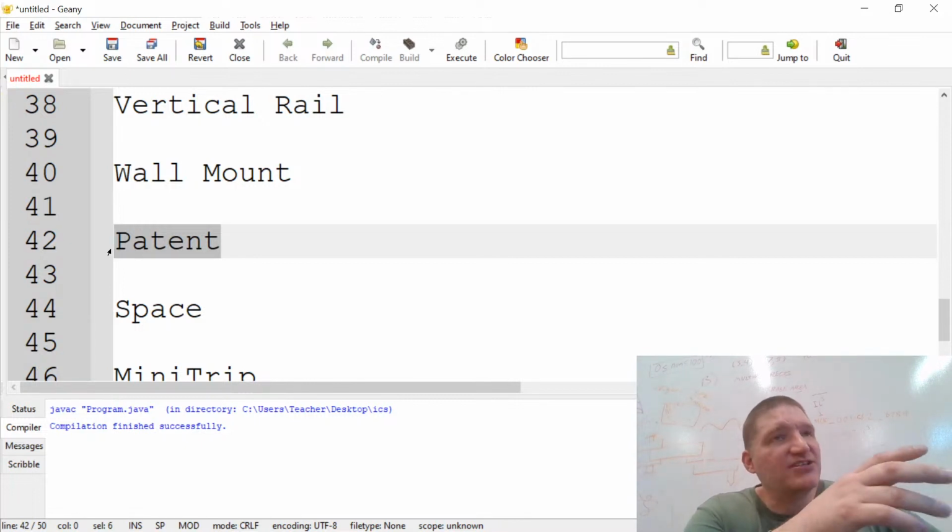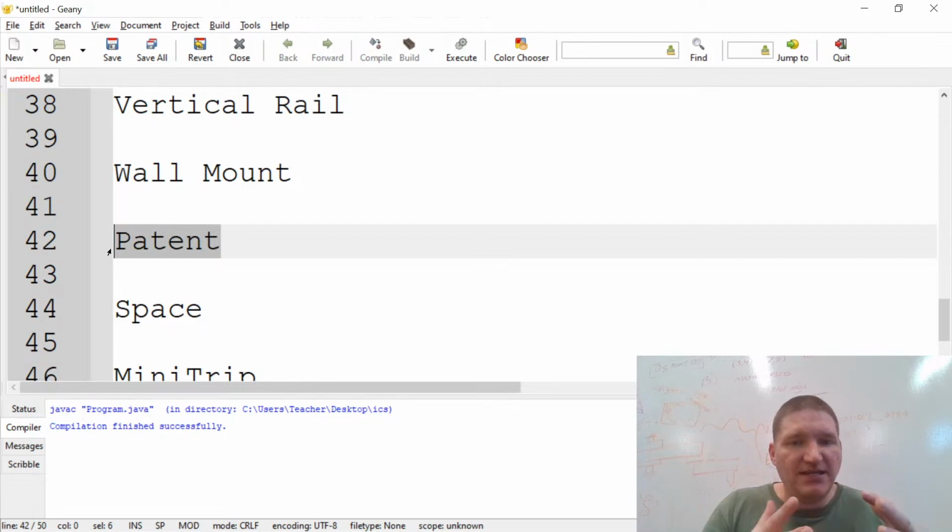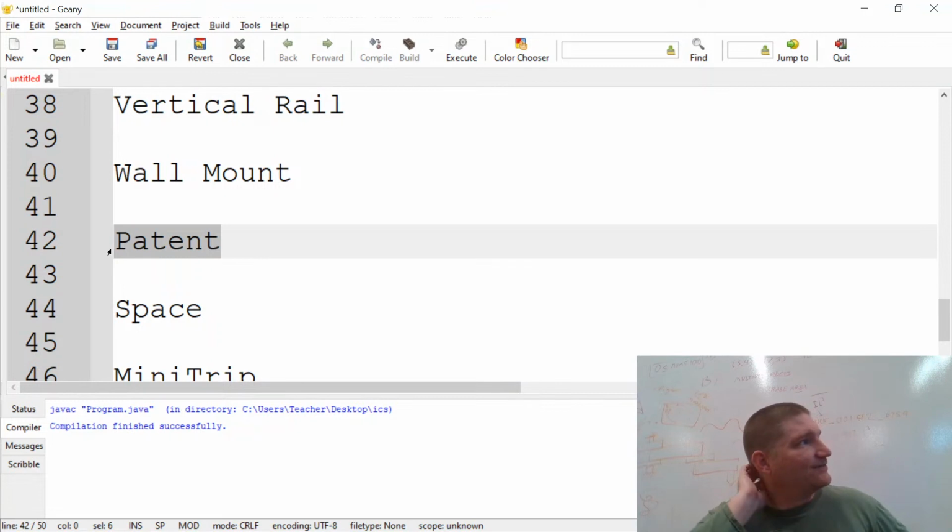The reason we think it skirts the patent is that the Tripteron patent says that each of the axes are decoupled from each other and uniform in the way they enter. In this case, I have asymmetric ways I tilt each of the carriages to accomplish what I want. So I don't get a nice decoupling, and I make my life a little harder, slightly, on the firmware side. So I think I don't infringe on the patent.